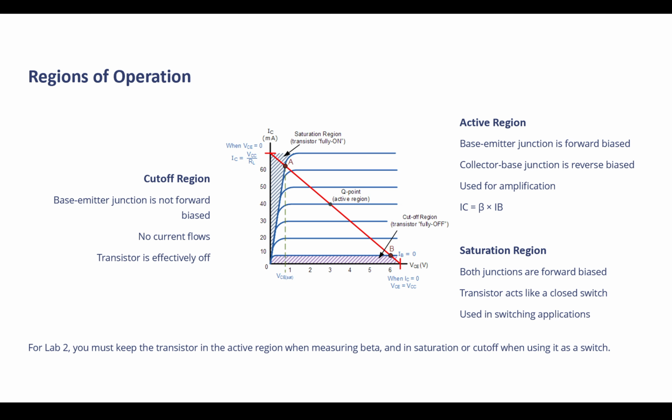Now, same concept as we talked about with the MOSFET goes for the BJT. If you don't apply any current into the base, the collector and emitter will see two diodes back to back, or in the opposite way. So no current. Doesn't matter how much voltage you have between the collector and emitter, you would not conduct any current between them.